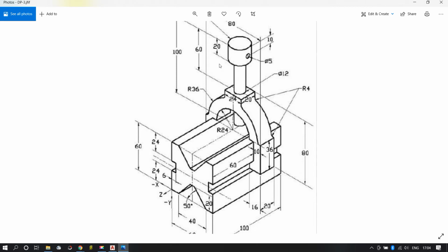And what will be your strategy about these two? How do you draw these shafts? Will you draw these shafts? Directly you can draw two circles. One circle, then press and pull, then another circle, and it will be simply connected. Then you first solid union these two objects, then you bring it and place it here.